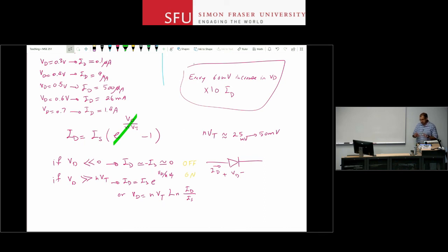And that's that for the semiconductor PN junctions. So we have a device that looks like an ideal diode whose characteristic curve is shifted a little bit to the right. There's a little bit of curvature to it instead of the abrupt change from short circuit to open circuit. This is a more gradual change. But nonetheless, the change is so sharp and so fast that we can use it as a diode, or something similar to a diode. And from the next topic, the next recording, we're going to solve circuits that have diodes in them, semiconductor PN junctions in them.